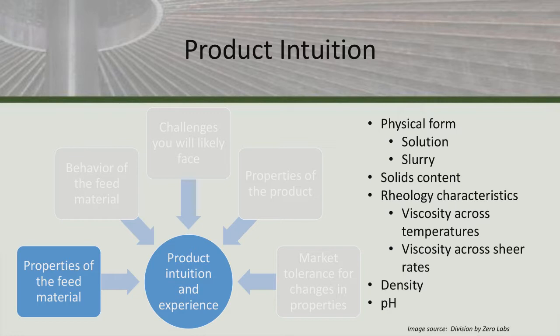What are the rheology characteristics of it? Viscosity will change across temperatures, but it's something you should measure. Will this be pumpable from a tanker truck when it's 10 below zero in Minnesota in the winter? You know, how does the viscosity change across shear rates? This is important because all atomization methods introduce high shear. If you've got a non-Newtonian fluid, this might prohibit it from being spray dried.